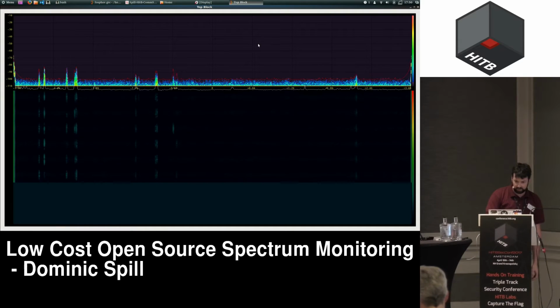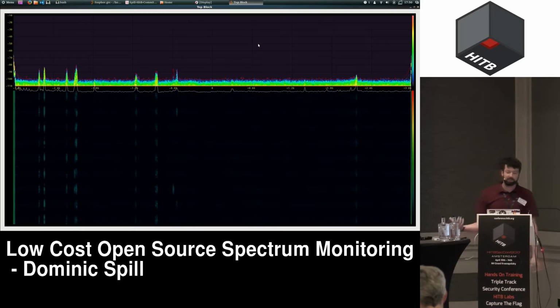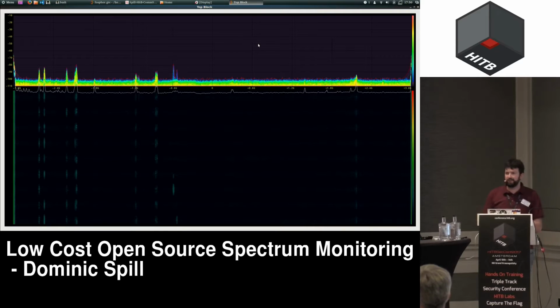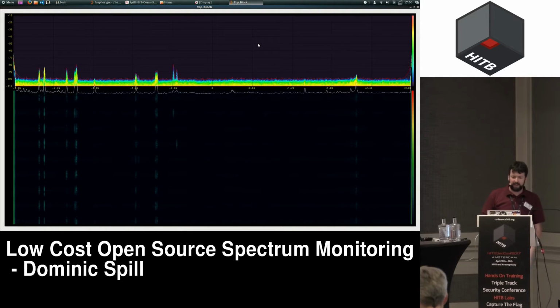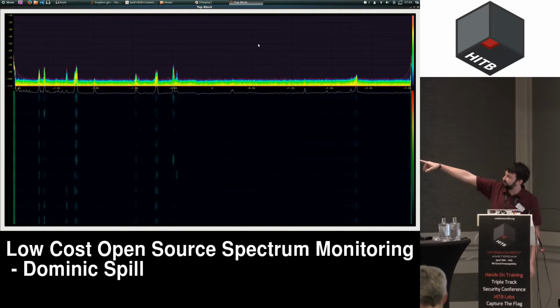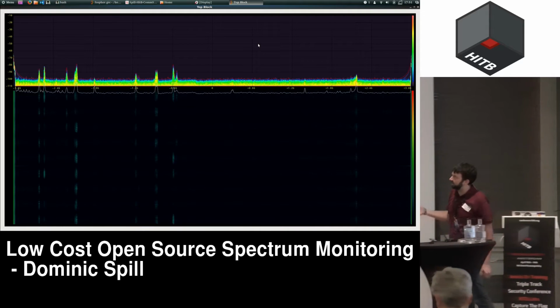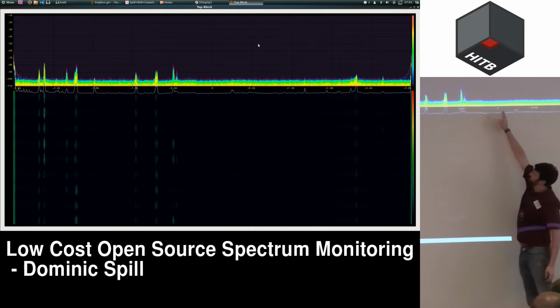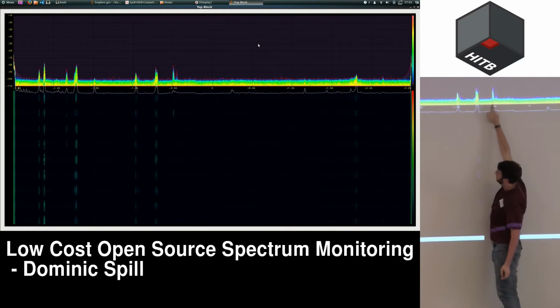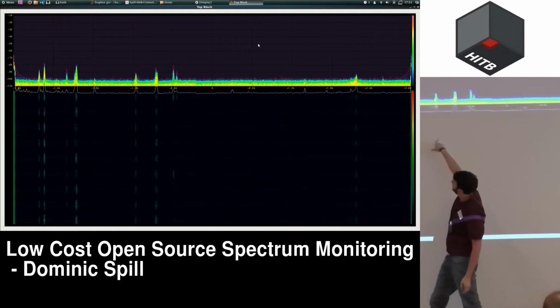And so what we should be able to see now is, again, doing the same thing, sweeping over 6 gigahertz wide, and it's performing an FFT over every 500 kilohertz, and then plotting that using GR phosphor. So you'll probably be used to this if you've used software-defined radio in the past couple of years to look for signals. This is very good at showing you transient signals, and we can see the 2.4 gigahertz section again. We're looking at 6 gigahertz wide here, with the 0 point in the middle. So negative 0.6, that's the 2.4 gigahertz spectrum, and various other things.